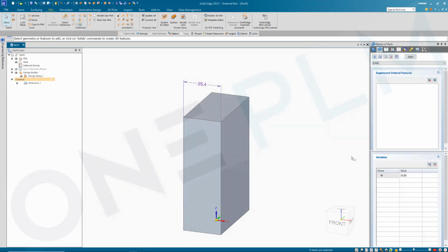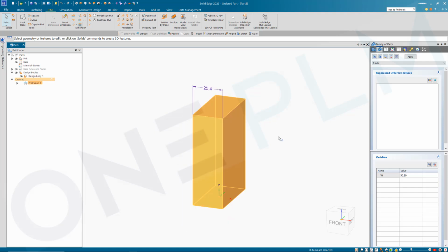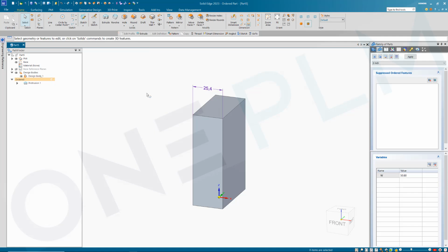And then select OK on there. And that's going to get added down here automatically. So now we want some kind of text on here that's going to represent the size of these. One thing worth noting: if we do a cutout or text in a sketch that changes, we want to do it as a sketch and then a cut. It's more predictable, more reliable that way. So doing a sketch is going to be better.